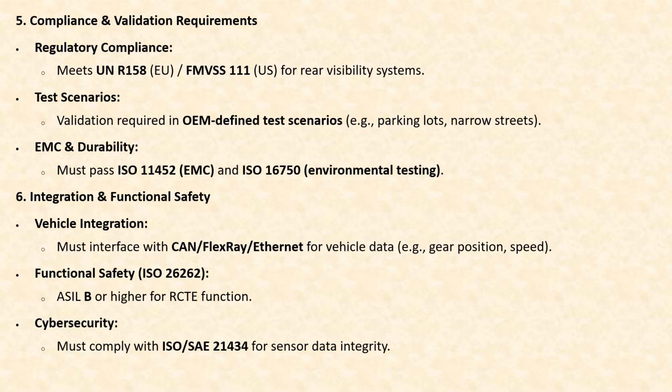And of course, the legal compliance requirements: you should meet UN R158 European norms or FMVSS 111 US norms for rear visibility systems. Next is the test scenarios or the test cases. Validation required in OEM defined test cases like parking lots, narrow streets. These are all the various test cases where this should be tested to prove its efficacy.